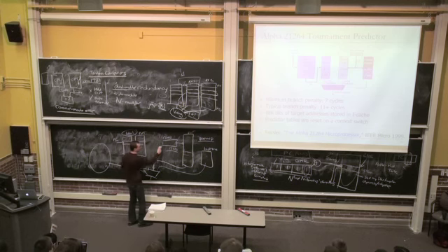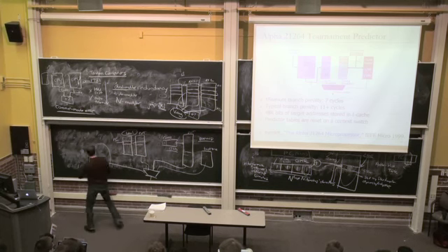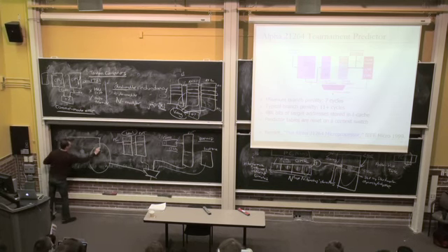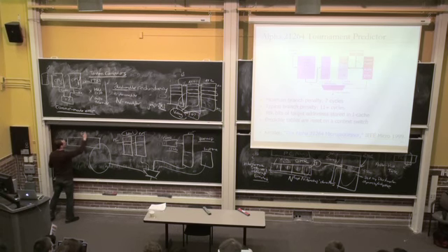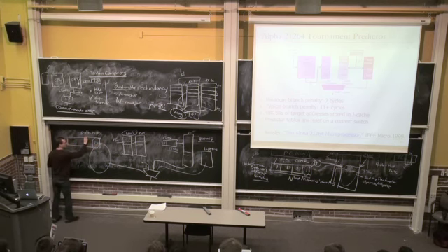Some other people have proposed, instead of using this history register with 1 bit per branch, let me just give you the idea. Instead of 1 bit per branch, you can do this. This is called a path history predictor, if you will. Instead of taken or not taken, you take 2 bits from each program counter.